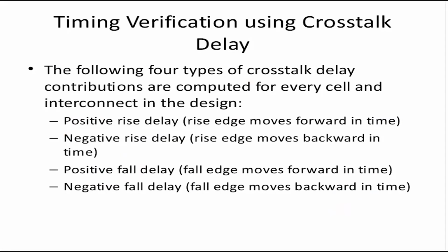So timing verification: noise is a separate analysis, but crosstalk comes into our setup hold domain because the delays are affected. Any physical effect that causes the delay to change will change your timing analysis, right? It will make it more difficult for you. Timing verification using crosstalk delay is computed for every cell and interconnect. In fact, it is a net effect, not a cell effect.